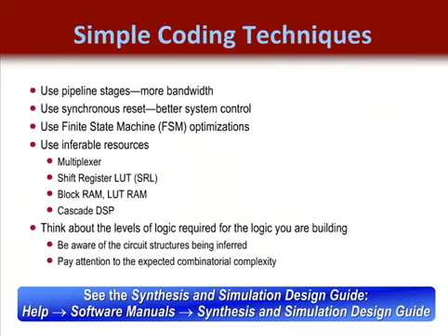This slide is trying to highlight some of the benefits of using good HDL coding techniques. Not only do users have to be aware that not all FPGA resources are easily inferable and that they have to make sure they are getting the best resources, but designers have to be able to find their timing critical paths and then recode. This is usually done by designers adding timing constraints during synthesis and then finding those paths with their schematic viewer. Likewise, while building their design, most customers know that they should use synchronous sets and resets and how to add pipeline stages.